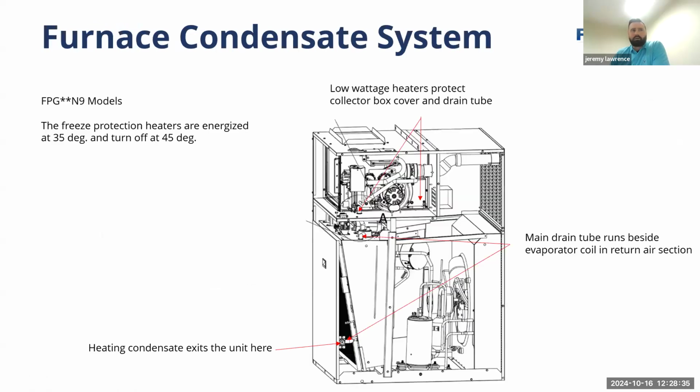Because we're working in cold climates, we do need to take some extra precautions whenever we're working with condensing furnaces or with low ambient heat pumps. They have taken extra precaution in both the First Pack units and the Fresh Pack units with extra insulation to protect, and in this case, there are actual heaters built into this unit to keep the condensate from freezing.